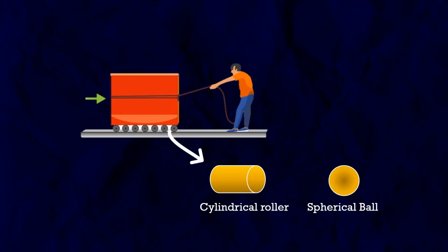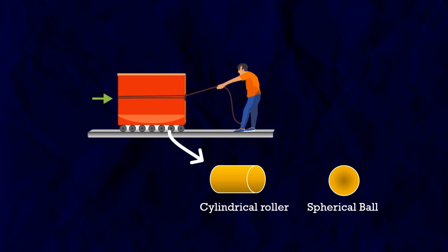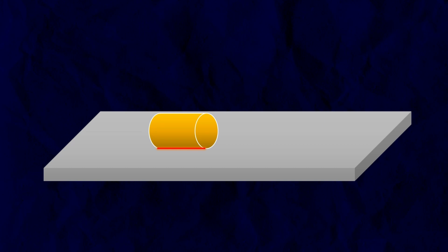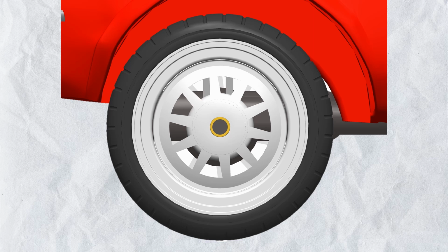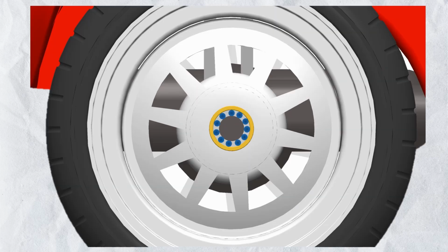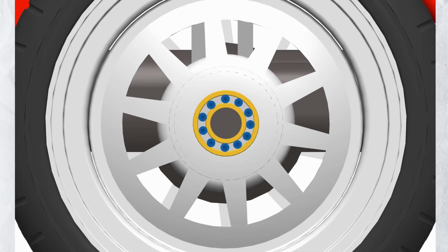One, a cylindrical metallic roller, or second, a spherical metallic roller. Cylindrical metallic rollers make line contact, and the spherical metallic roller, like a metallic ball, makes point contact. So the balls make minimum surface contact. So let's put the metallic balls around the shaft, something like this. But the load is heavy and the contact with the ball is pointed and sharp, so it could dent the shaft. So we have to add one more hardened bush over the shaft also.